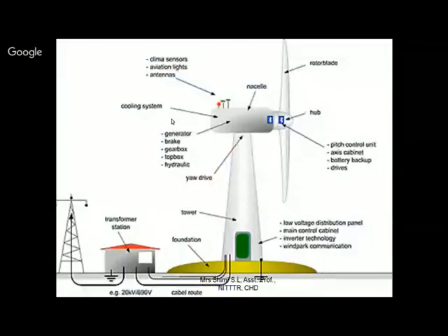So actually this wind turbine, if you see, generates electricity in the form of AC. So that AC cannot be directly given to the grid. First of all, some conversion is required. This AC is also not continuous, as I said. It is a varying AC. So what we usually do, we convert that into DC. Then DC to DC conversion, and again DC to AC conversion, so you can convert according to our requirement of frequency, because 50 hertz is required, and whichever transformation has to be done is done, and then it is stepped up or stepped down using transformers and then given to the grid.